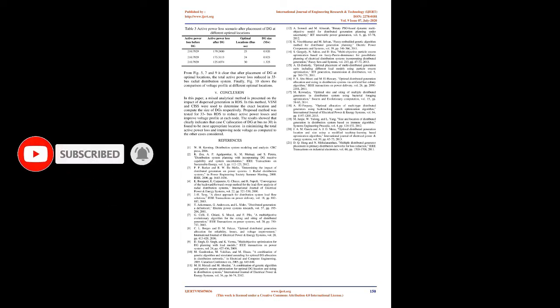From Fig 5, 7, and 9 it is clear that after placement of DG at optimal locations, the total active power loss is reduced in the 33 bus radial distribution system. Finally, Fig 10 shows the comparison of voltage profile at different optimal locations.